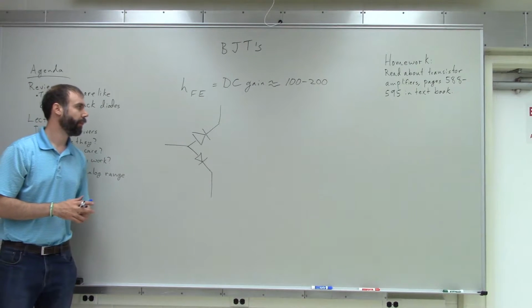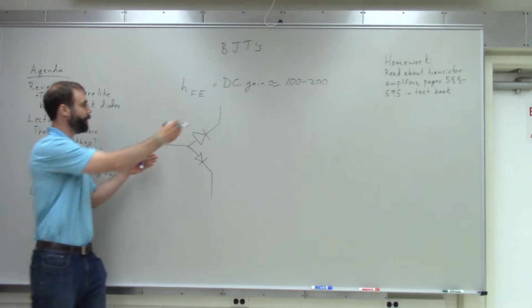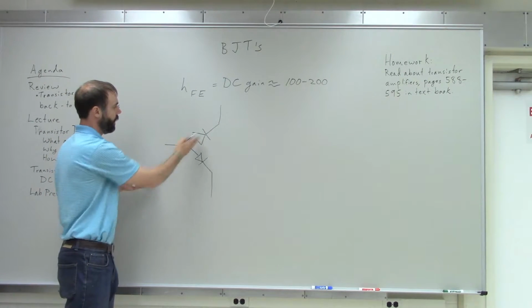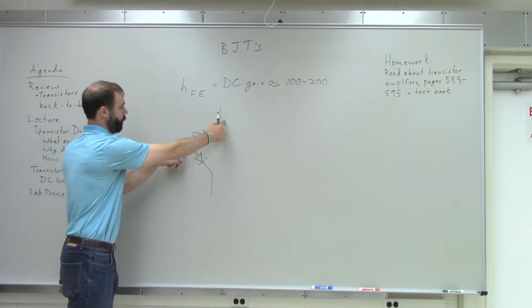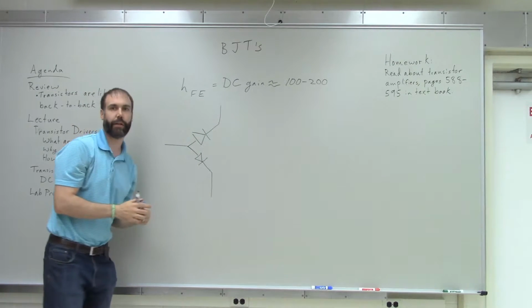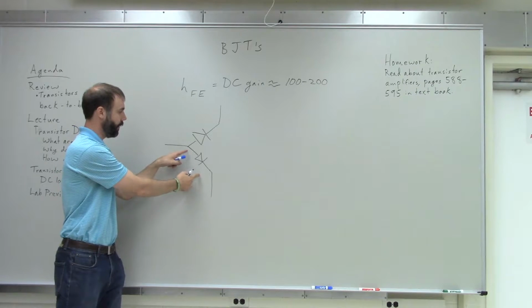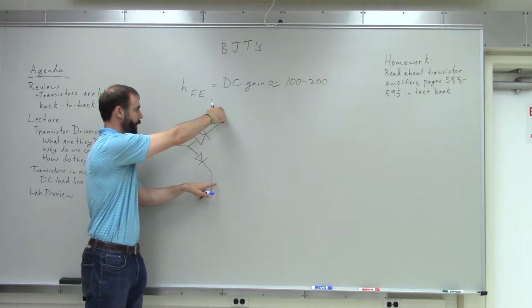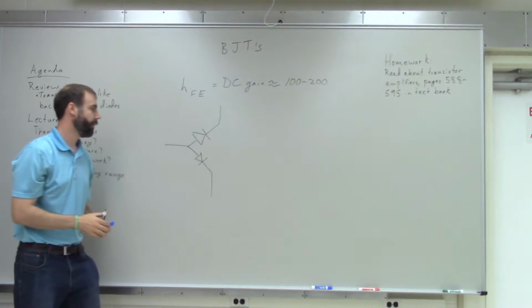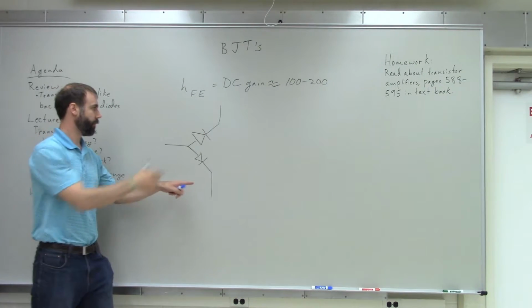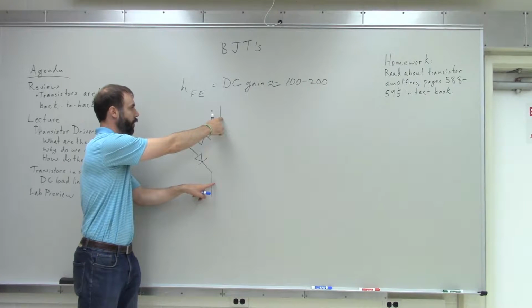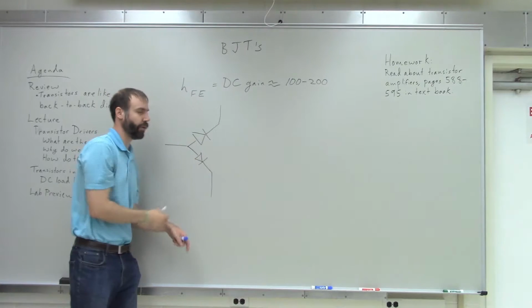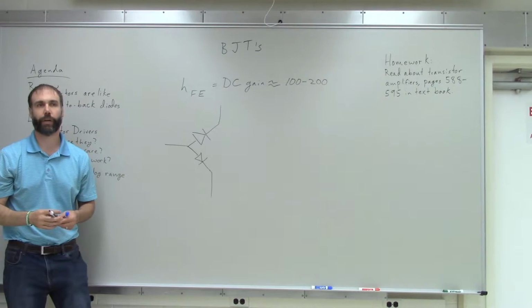So we used our multimeter, and we measured between here and here, and we checked to see that the diode was forward biased in one direction and reverse biased in the other direction. We did the same thing down here, and then we also measured between these 2 points, and we found that there was always an open circuit, an overload between those 2 points, because one diode or the other would always be reverse biased, right?